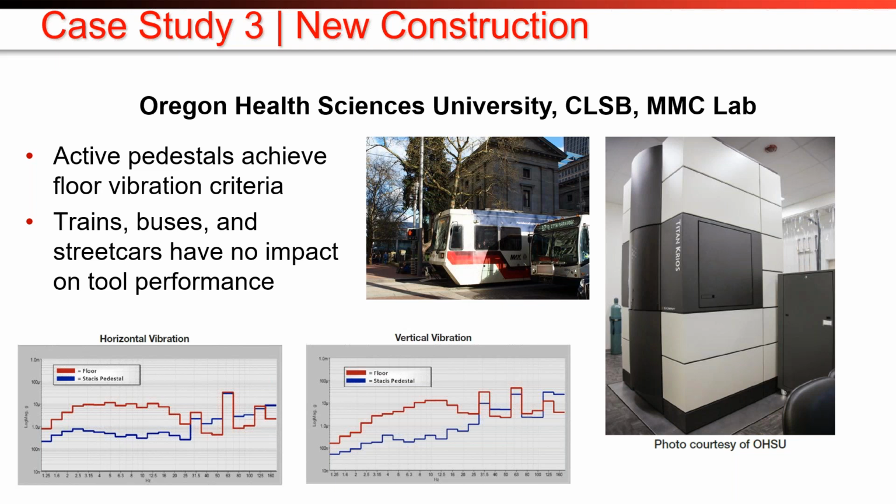You can see in the curves again, the red curve is the floor and the blue curve is the isolated platform. And once you get above 30 hertz or so, you don't see any vibration isolation. Well, in fact, it is isolating. That's just evidence that above 30 hertz or so, your isolated levels are really controlled by energy coupling in from acoustics and other structures, other paths, rather than vibration coming up through the floor.